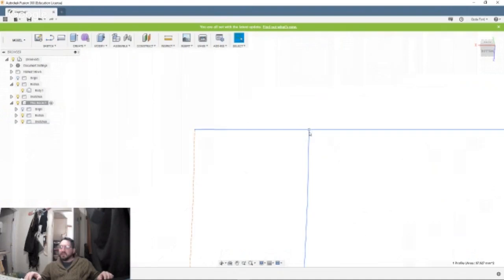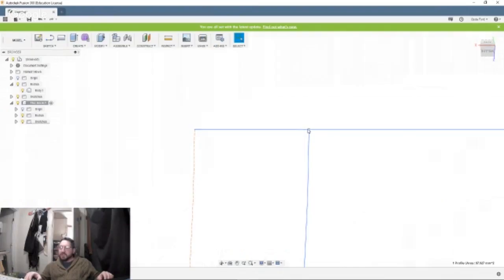Like right there in that upper corner, right there somewhere. No, that's meeting. Nah, I don't know if it's. Yeah, but it's overlapping. Well, hit that point and go over to your sketch palette. Just that point right there. Go over to your sketch palette and say coincidence, and it will line up to that line.